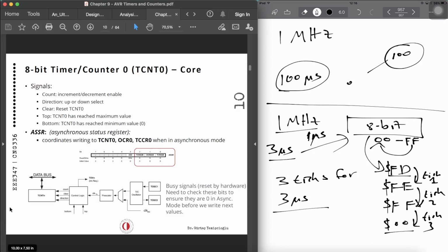So it means it contains zeros and it counts up from each pulse, and the contents of the timer counter register can be accessed using this TCNT register. You can either load a value into the TCNT register or you can read a value from it.